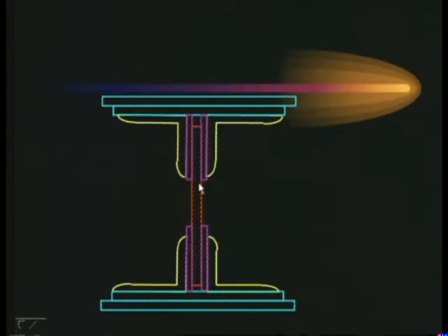That means it can resist more loads, much heavier loads. See here, there is a web plate. There are 2 plates at the top, 2 plates at the bottom, 4 flange angles, and these plates are the filler plates or packing plates, you can call them.